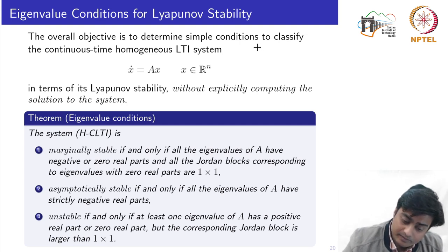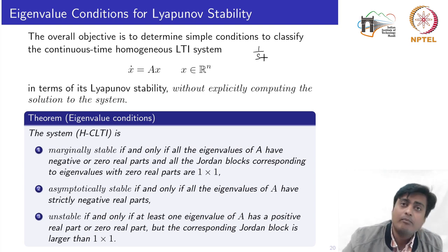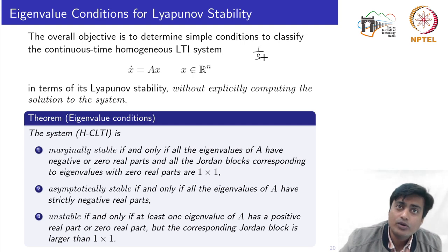Here is one important thing if you want to relate it to transfer functions. Let's say we have a transfer function given by 1 by s, a simple integrator. For any constant input, you would see that the response is rising, it would integrate. And for any initial condition, the response would become constant. So if I am using the integrator with respect to the initial condition, then it would be bounded, right? But it won't be asymptotically stable, because the response will never go towards 0.